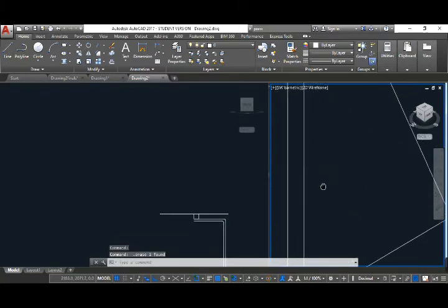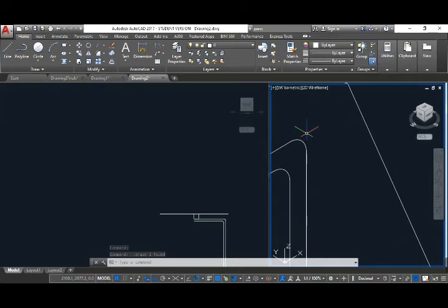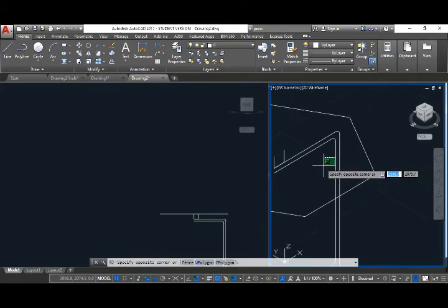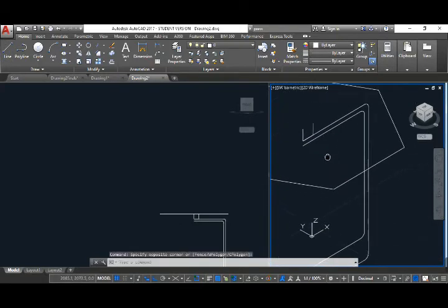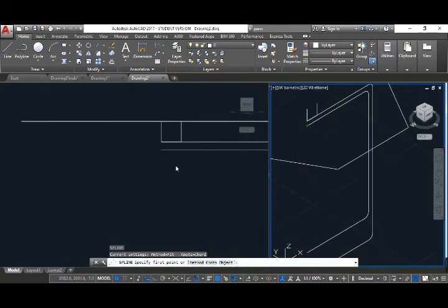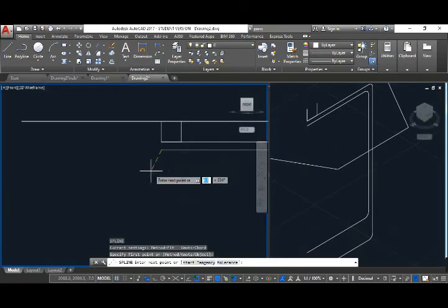At this point, we're going to make the straw where the perfume should come out. So we're going to use the spline command here. We're going to click on the center of the inner wall as the start of the tube.